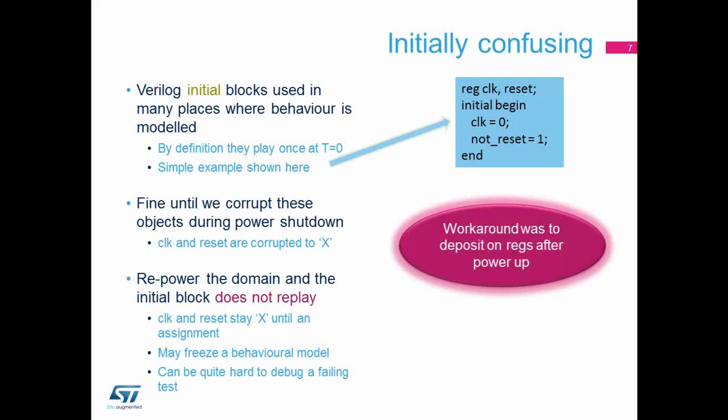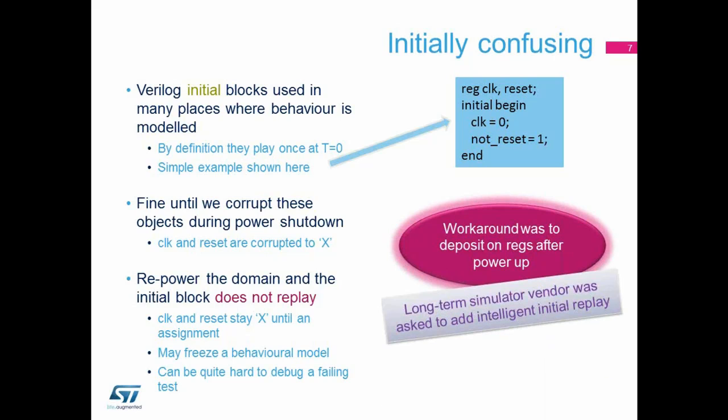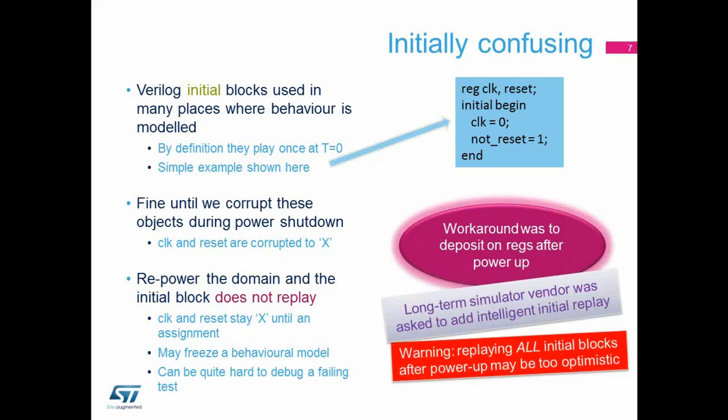We had to deposit values on these, in this case, clock and not reset, to mimic what the initial block would have done. The long-term solution was to ask the simulator vendor to replay the initial blocks as though it were time zero, but there's a warning here, because if you just blindly replay all initial blocks, you might find that's over-optimistic for verification. You may be giving too much back.